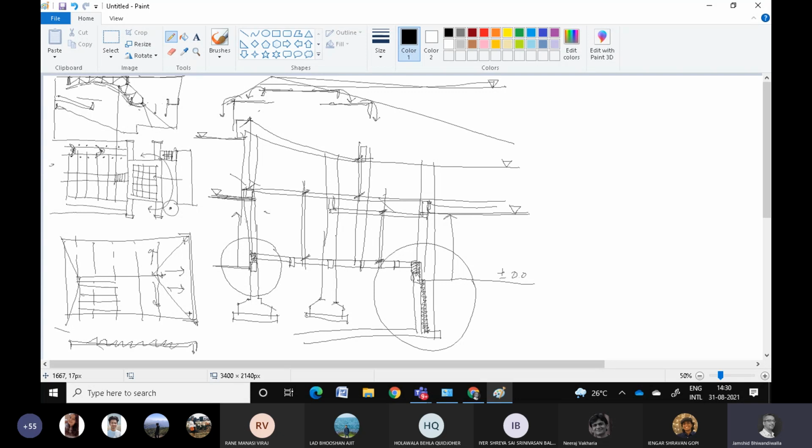So I've given you an idea that floor to floor height and beam bottom levels are all that is expected, preferably in a well drawn, technically right section. Not to forget, most people also put the center lines in place.